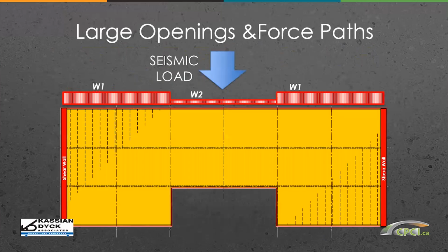So this is a diaphragm with a big notch out in the middle. And if I said, oh, if this was a beam, and let's think of the left and the right-hand side as supports subject to this uniform load, we'd know, wow, we're going to have to really look at that as a beam design and decide what our model is, how we're going to analyze it, how we're going to reinforce it, and accommodate that large penetration in the middle. So again, we need to carefully examine that and look at it.